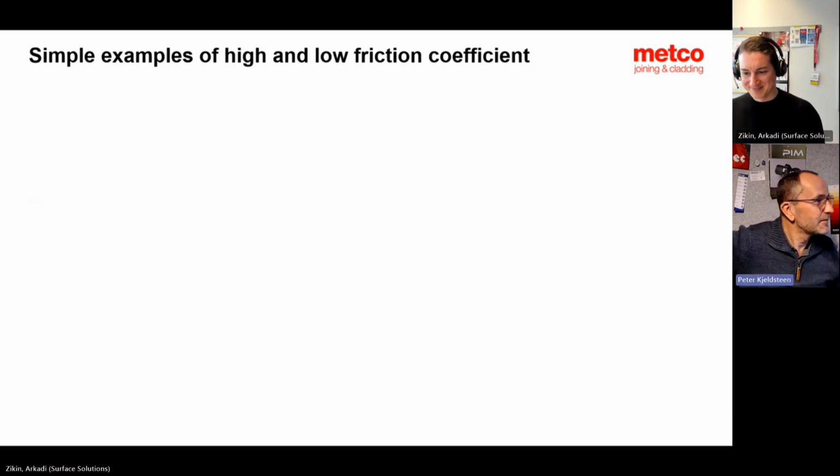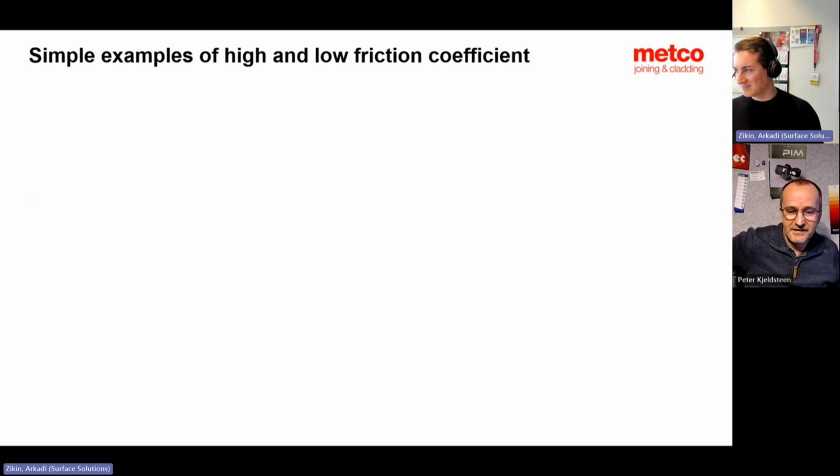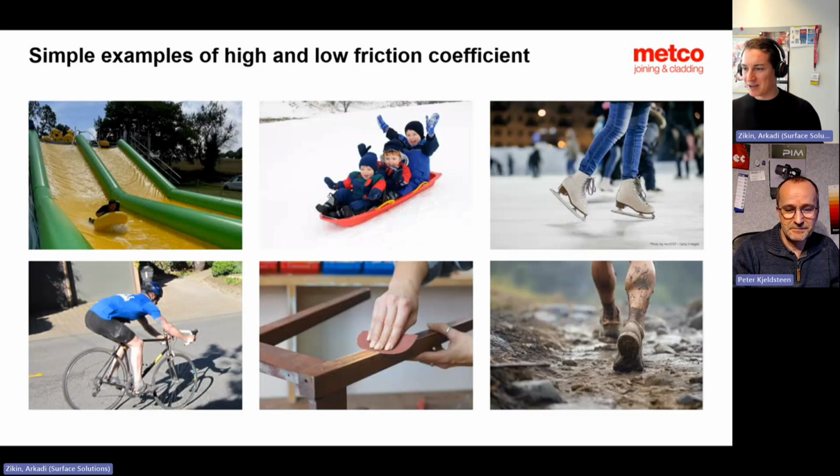We use ourselves tungsten-based hard metal against silicon carbide, lubricated with water. It has a very low friction coefficient, thanks to lubrication at the same time. I was not thinking about the scientific approach because we probably have people who watch us who have no idea what we talk about. So I gave this type of examples from a normal life.